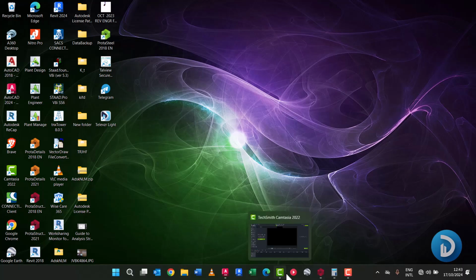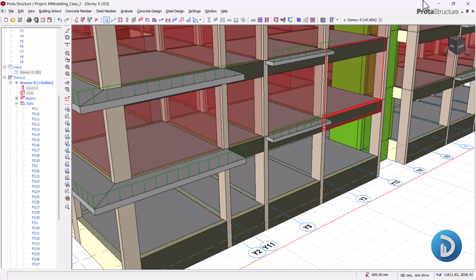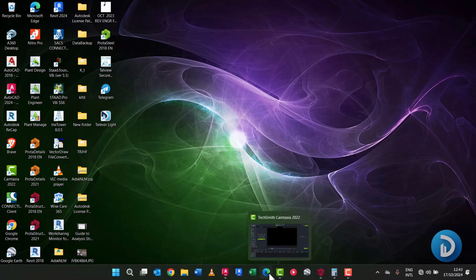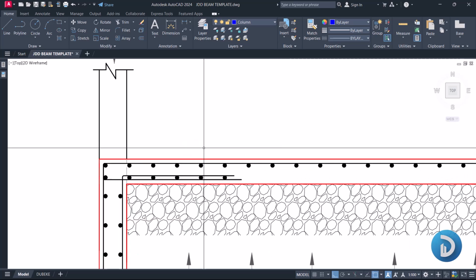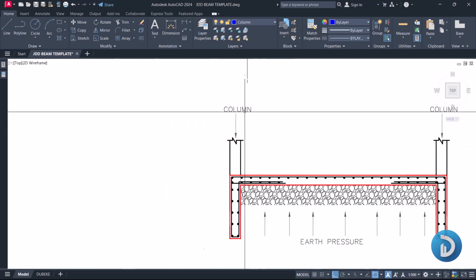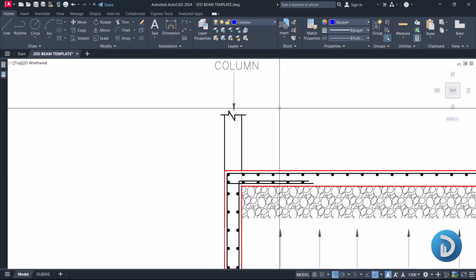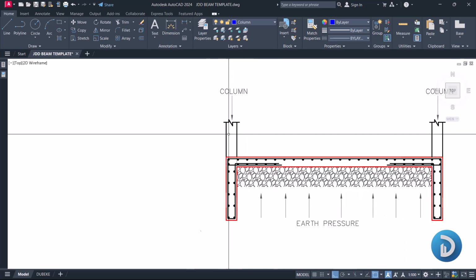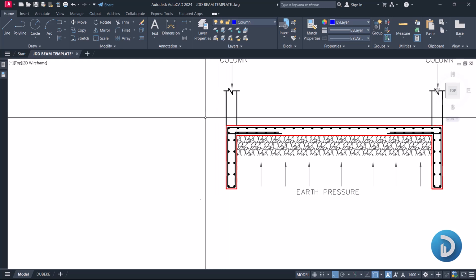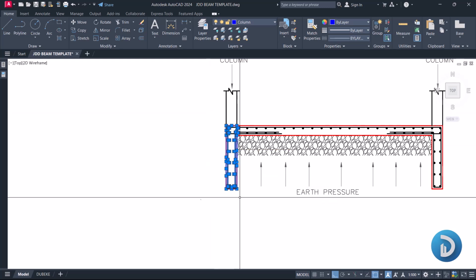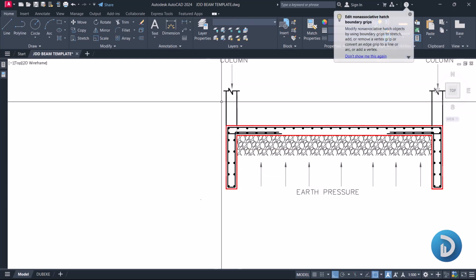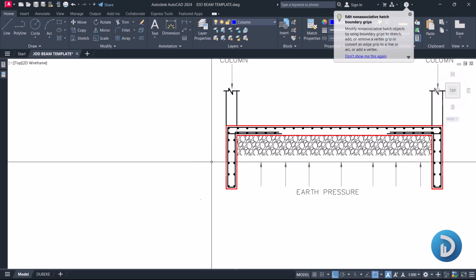On getting to the substructure, the magnitude of load that is coming from our column will cause a high magnitude of punching shear. So our beams will eliminate that punching stress that is coming from the superstructure due to its effective depth.